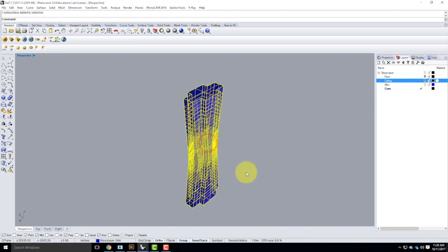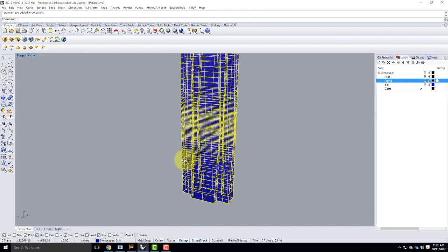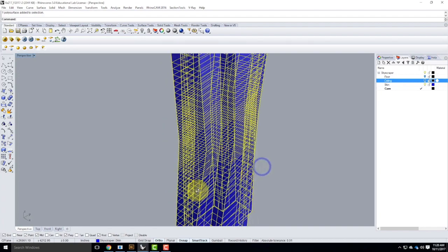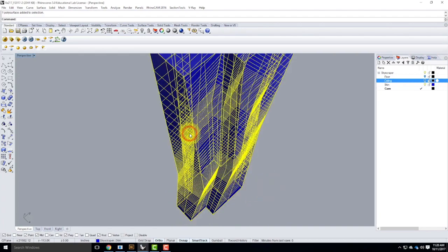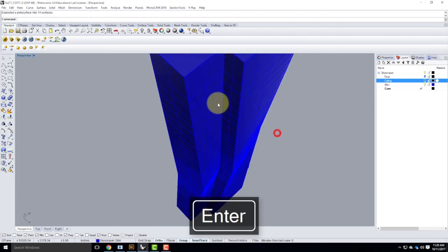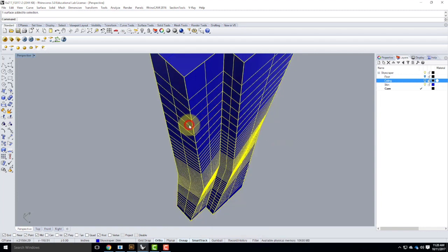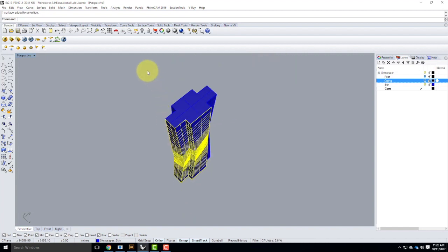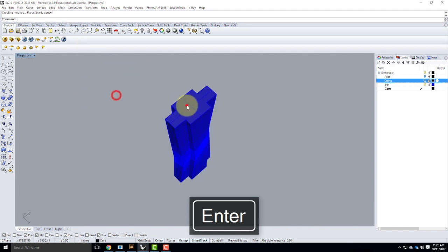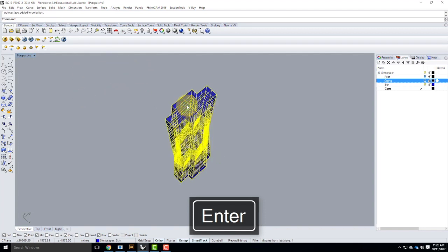And so the first thing that I need to make sure is that this shape is joined together into a closed polygon. So if your shape has a bunch of individual pieces like this, you're going to want to make sure you take all those pieces and join them together. The hope is that they come together rather nicely. So I'll take those pieces, I'll type join, and they do come into a nice joined polysurface.